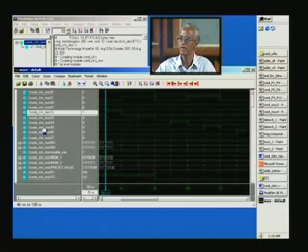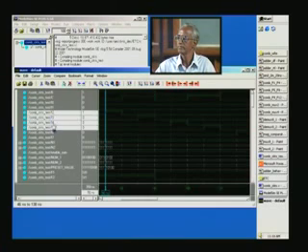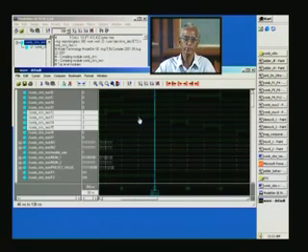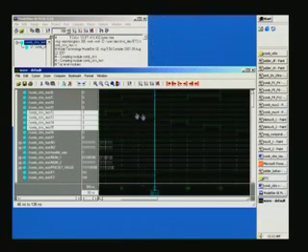Suppose I have more than one or two signals. Let us see, we will use the other arrow this time. So it has gone to the negative transition of I2, and with this it has gone to the negative transition of I3. Maybe we'll have to find out why it did not go to this. So you'll have to experiment with it and get a feel of the tool as such. This is a basic thing that you can utilize for your benefit, going from one transition to another.